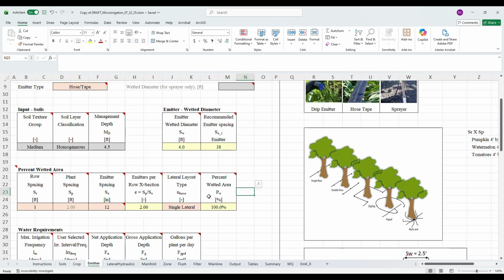For this problem, you might be able to talk with the landowner about whether or not they need 4 drip tapes per bed, or if just 1 or 2 would be adequate. In this case, if we go to 1 drip tape per bed, say we put that down the center of the bed, and then we have 2.5 feet to the outside of the bed, 2 feet walkway spacing, 2.5 feet to the other lateral, we would have 7-foot lateral spacing.